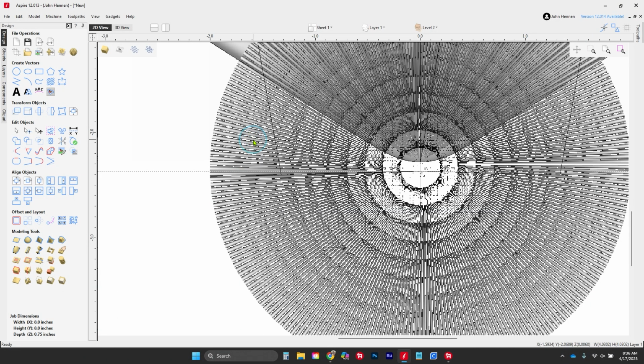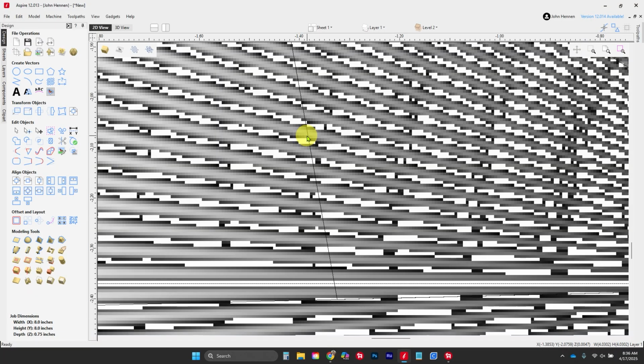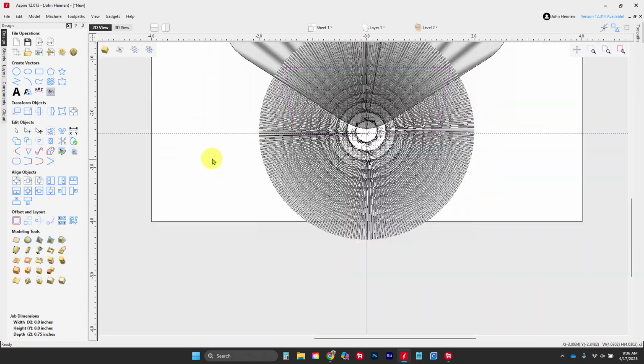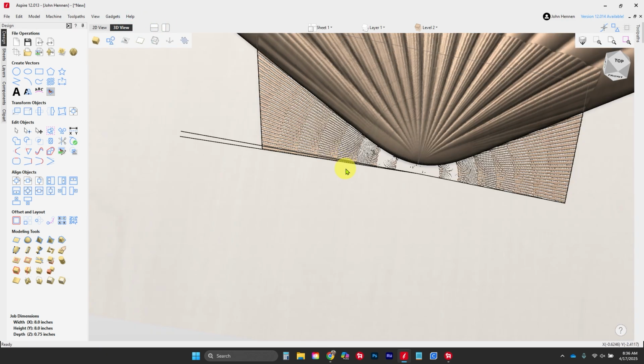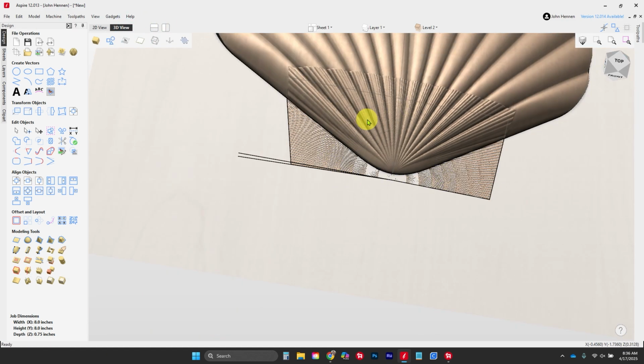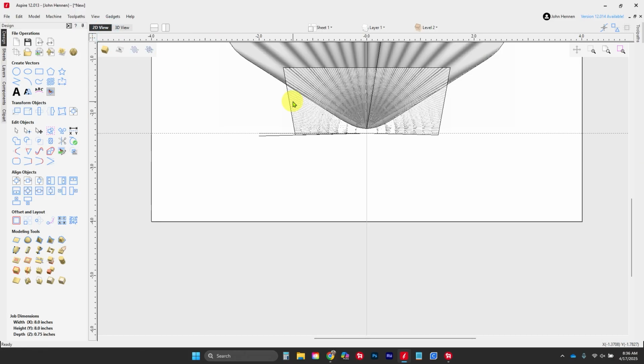So grab this guy here, hold down Shift, grab our vector again like we did before, and just kill everything outside of it. It's going to be this one here. That's just going to wipe everything out. So now we have just this little shape here. And again, it's really, really small. That's what we wanted. So let's build up our 2-rail sweep here.